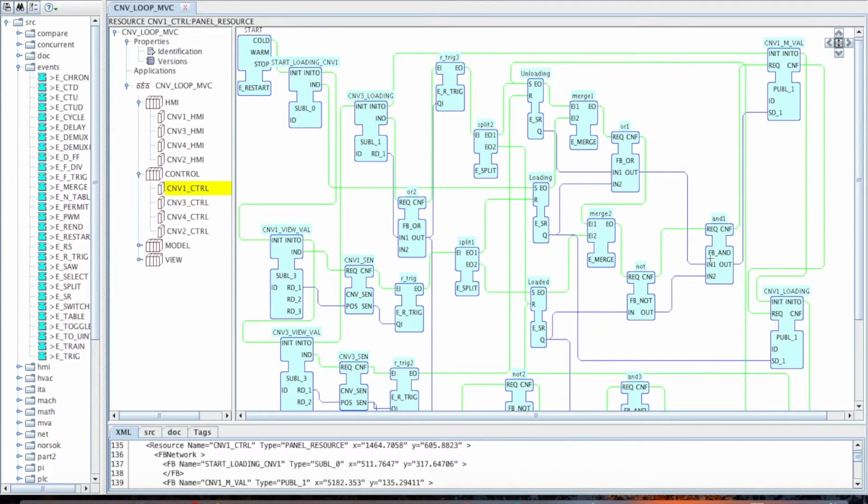What may add some additional connections, and you see here a merge block. As we have to integrate several event flows, it's recommended, or actually required by the standard, to use a merge block to integrate event flow between the blocks. So that's the output logic for the motor.